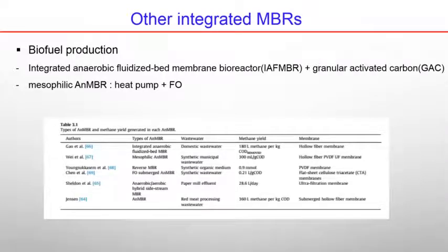For biofuel production, representatively, there is an integrated anaerobic fluidized bed membrane bioreactor combined with granular activated carbon. And it was developed to treat domestic wastewater with energy recovery. Integration of heat pump and FO in mesophilic AnMBR process would be a promising way to net energy recovery. This table below shows the types of MBR and methane yield generated in each MBR.